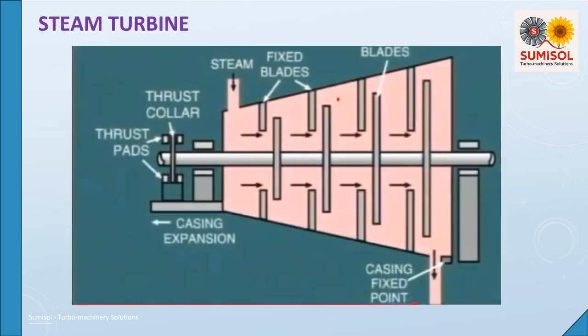In a steam turbine, axial shift refers to the movement of the rotor along the horizontal axial axis. While small axial movements are natural due to pressure differentials, excessive axial shift is dangerous and can lead to catastrophic failures. Axial shift is controlled by: 1. Thrust bearings, located at one end of the turbine shaft, which absorb axial loads and limit shaft movement. Tilting pad thrust bearings are commonly used.